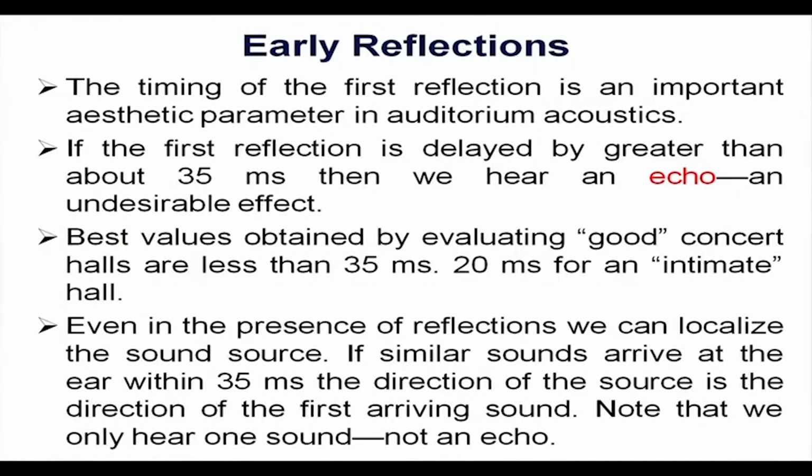The time of first reflection is an important aesthetic parameter in auditorium acoustics. If the first reflection is delayed by greater than 35 milliseconds, then what will happen? Echo will come, which is not desirable for an auditorium. So, the first reflection must be within 35 milliseconds. The best value obtained by evaluating good concert halls is less than 35 milliseconds, which is 20 milliseconds for an intimate